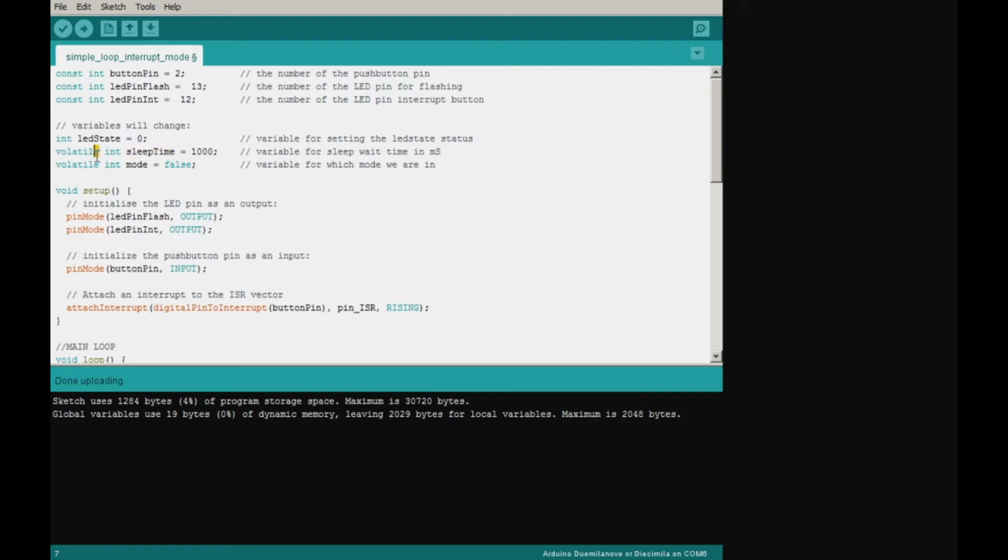So we use the volatile keyword to say, don't optimize it, it is getting changed and it is in use. Put it in the code. So if you like, we're one step ahead of what the optimization in the compiler thinks we want to do. We're telling it otherwise, and we're saying no, keep it in.